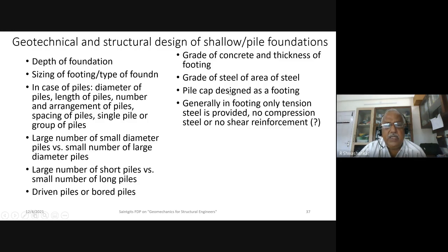Usually a group of piles are covered with a pile cap, and in design, what we are taught in textbooks is to make the footing or the pile cap safe in shear without any shear reinforcement. But many designers also use shear reinforcement. You know, shear reinforcement in beams is in the form of stirrups. In slabs like footings and pile caps, you can have vertical reinforcement between the top layer of reinforcement and the bottom layer of reinforcement.